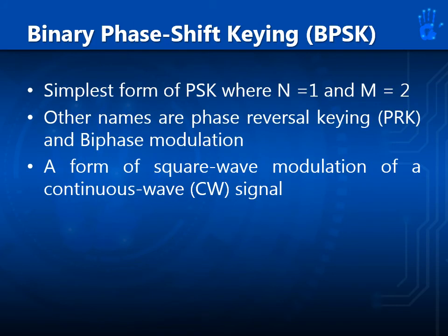Binary phase shift keying, or BPSK. BPSK is the simplest form of PSK, wherein n is equal to 1 and m is equal to 2. Other names are phase reversal keying, or PRK, and biphase modulation. This is a form of square wave modulation of a continuous wave signal.